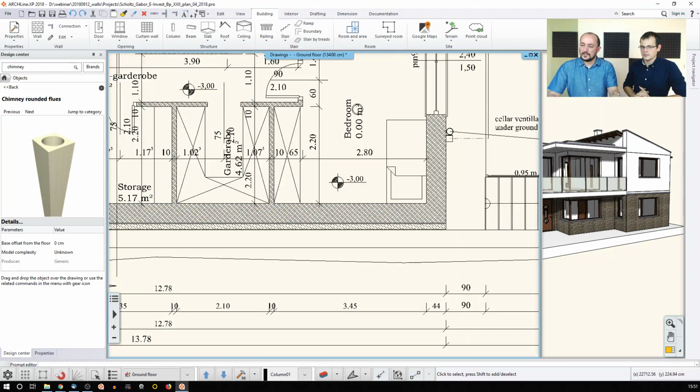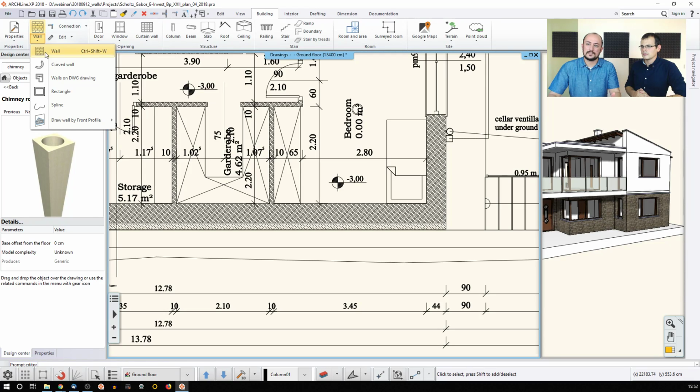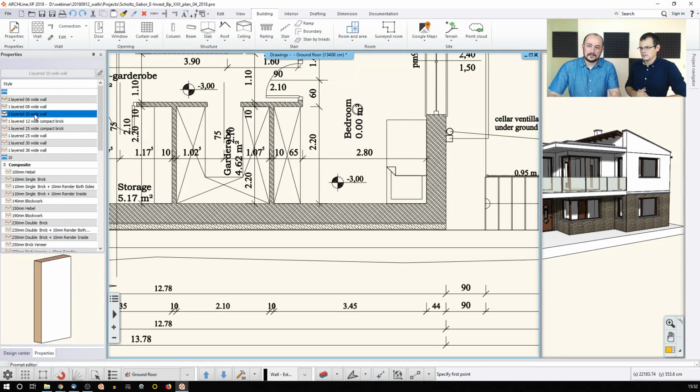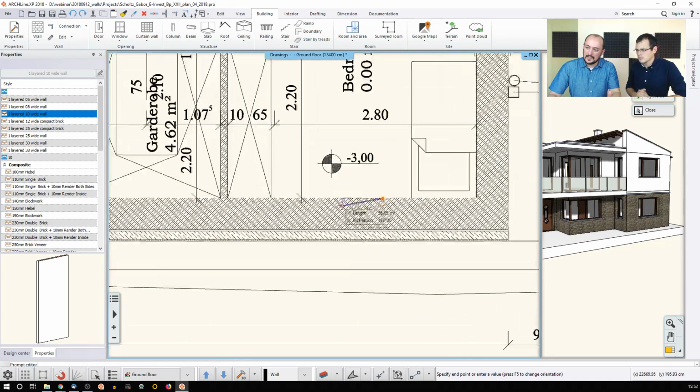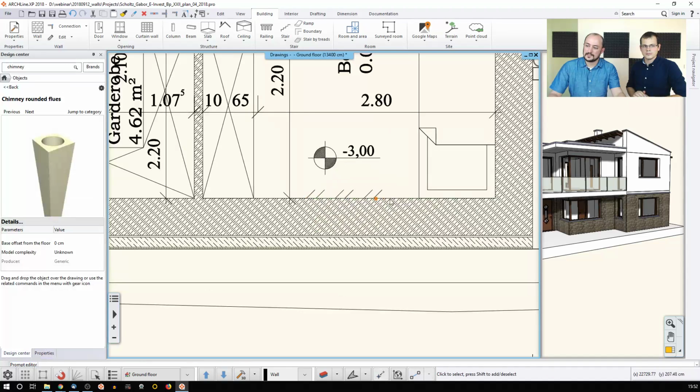Another solution is that you can add another wall here and then make changes on that. In that case, it's very simple. You just say that this wall is a 10mm wide wall which is lying in front of the other one. Again, take care how you draw it, because if it falls into the other one, you will confuse the connections. And so yeah, you just hit F5, and now it's there. So the software creates this wall structure there.